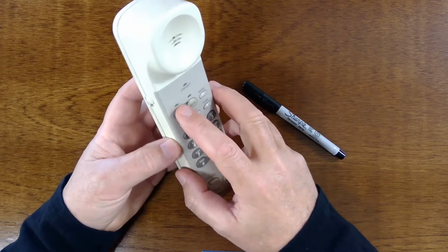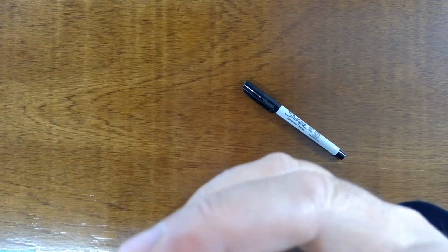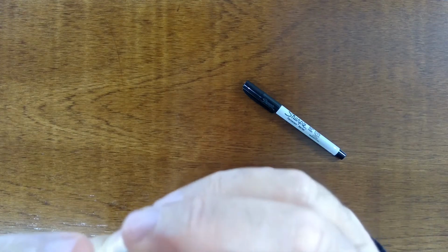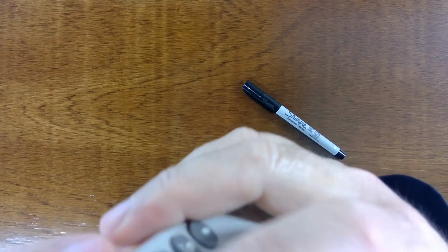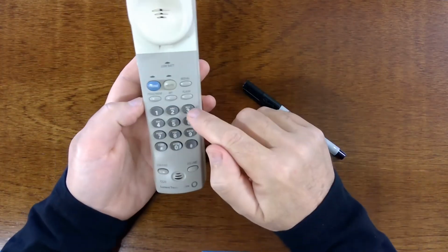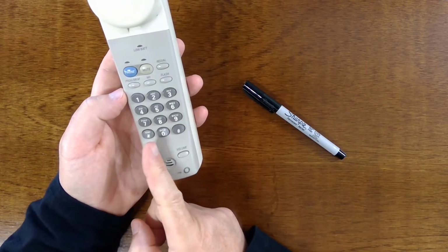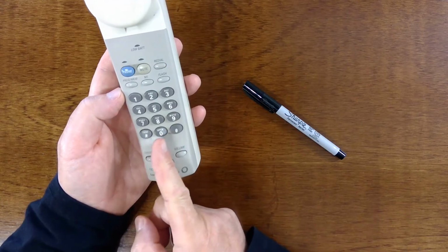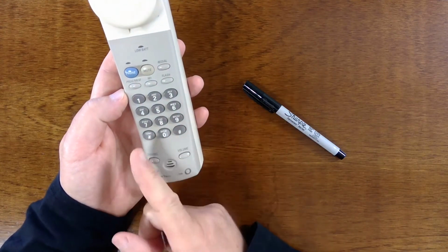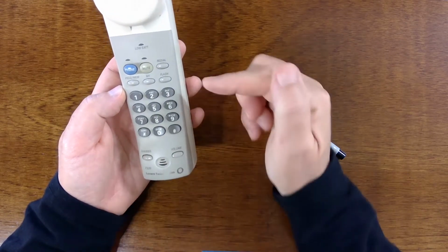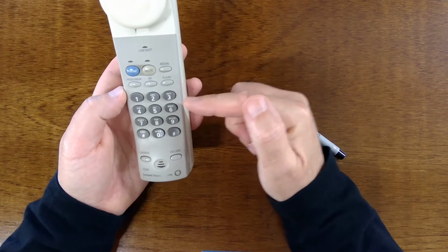And here, I'll turn this on and see if you can hear that. I don't know if that's turning it up, but there's two tones. Like when I push this button here, when I push the 3, there's two tones. So there's a set of frequencies. There's 3 frequencies along the columns, and that's called the high band. And then there's 4 frequencies on this way, so that's called the low band.